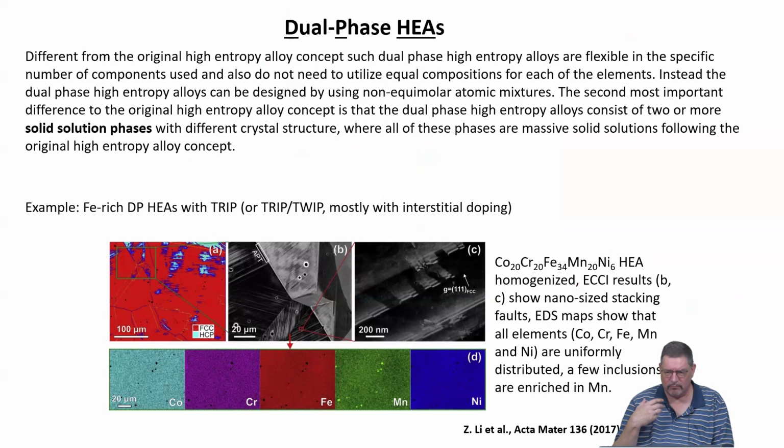These studies have been like a continuation from steel-based research, because if you think about steels, some of them actually have rather large concentrations of additional elements in addition to iron, and all of them have a high number of functional constituents. So typically like 10, 12, 13 constituent elements, each and every one of which has its own function to make higher strength or higher ductility, higher work hardening rate, and so on.